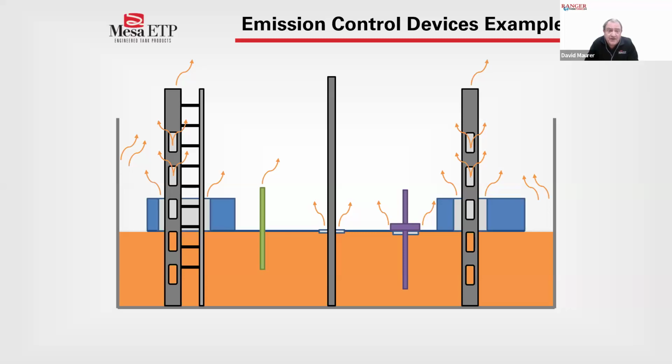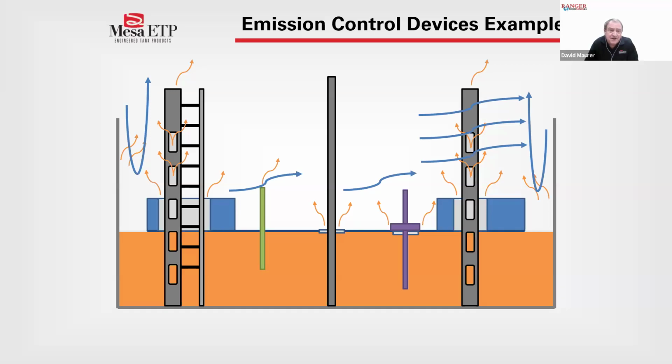So that is probably the next biggest area of emitting. And again, it's the rim space between the edge of the floating roof and the shell of the tank. And Adam just popped up here. We're also talking on external floating roofs as well as internal floating roofs, but not to the extent. But we get the Coke bottle effect, if you will. It's the wind blowing across of it actually sucks the vapors out and leads to increased emissions.